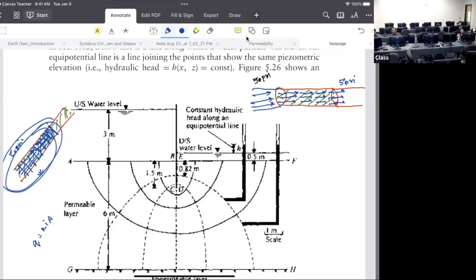Here, in the pipe flow, let's say, what is the hydraulic gradient within a unit length? Del H by del L. Water is flowing through it, right? So let's say at this point your water pressure is 40 psi, and then after a certain point it becomes 35 psi because it's dropping.